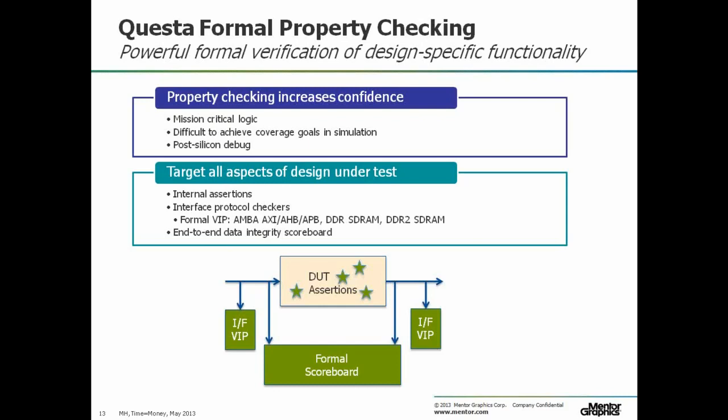It was mentioned about post-silicon debug before. So again, another application: trying to capture the signature of the failure you see in simulation, defining that as some property set, typically quite a few properties maybe, and proving or trying to find that bug using formal. The beauty of using formal for post-silicon debug that wasn't mentioned is that when you demonstrate the bug in formal, you can fix it in the RTL and prove the fix in formal as well. So before you commit to the costly respin, you're actually proving that you fixed the bug, or at least the one you're currently looking at anyway.